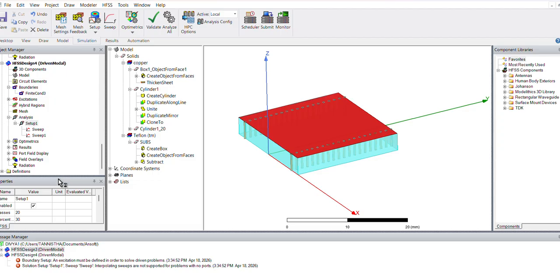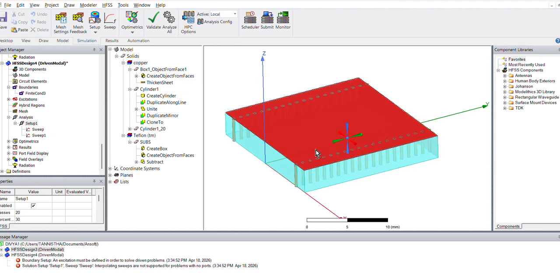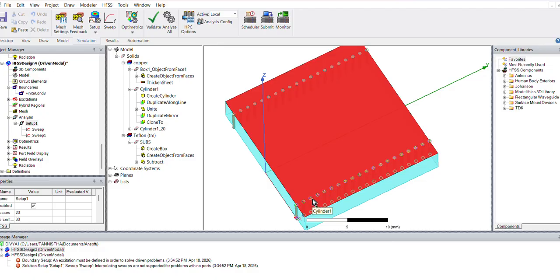What we are trying to see is, we started from a normal waveguide. We made it into a dielectric waveguide. Now we made that into a SIW and we are seeing whether the results are the same. Effectively, the result should be similar at least. The only thing is, because the PTHs have a round structure, it is going a little bit inside also, right?